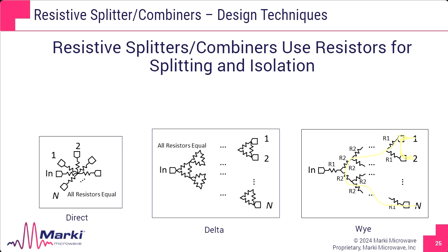Likewise here, we see the insertion loss from any one input to output is the exact same path as any output to output. So this is a case where your insertion loss and your isolation are equal. These two are cases where they can be equal, they can be a little bit better, a little bit less, but you're never going to get great broadband isolation across all ports.